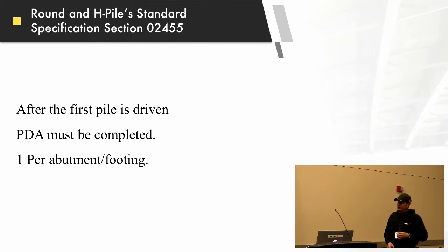They're there to make money, and I understand that. They'll continue to drive that abutment or that footing as much as they can for a full day's production, and then knowing that, they're coming back the next morning with the geotech engineers and running a complete PDA on it to get a driving criteria.